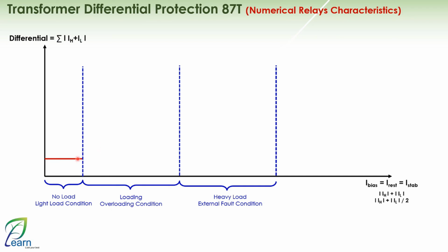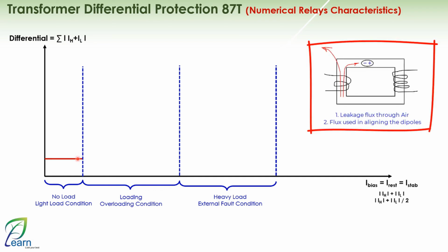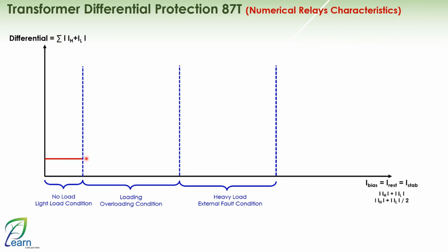these currents or other currents, and subsequently what will further happen to this in the process. It will appear more prominently as a result of what? As a result of the increased load you have. Therefore, this will require you to raise the value. Similarly, in the case of heavy load and external voltage, the ratio error will increase significantly, in addition to the possibility of CT saturation for one of the CTs only, while the other CT will not be saturated. This will create a very large difference, and the transformer's response will also be planned by raising the differential value